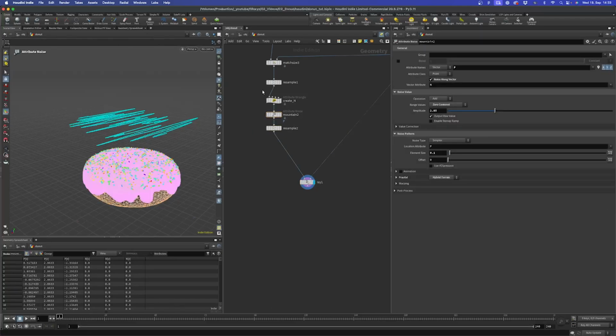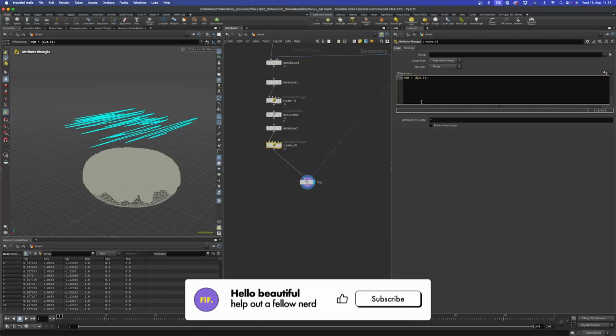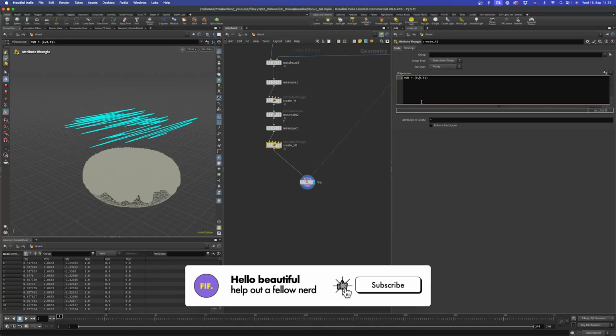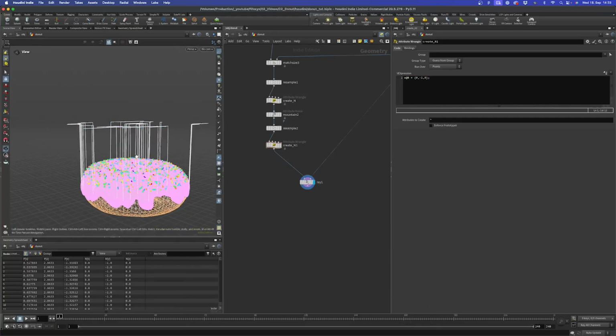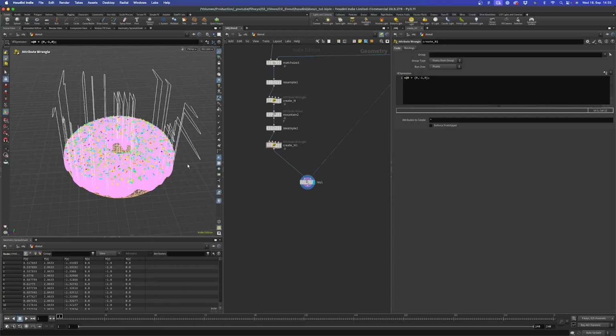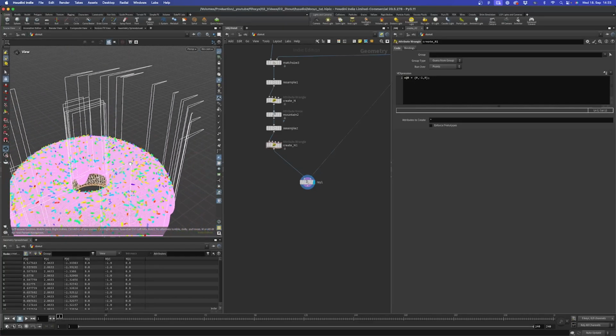But currently it will shoot in the normal direction, and our normal direction is in the X position. So let's just copy over this node so we don't need to rewrite our code. We just change it from the X direction to the negative Y direction. And boom, you can see our lines are going to be projected onto our surface. Perfect, that's exactly what we want.